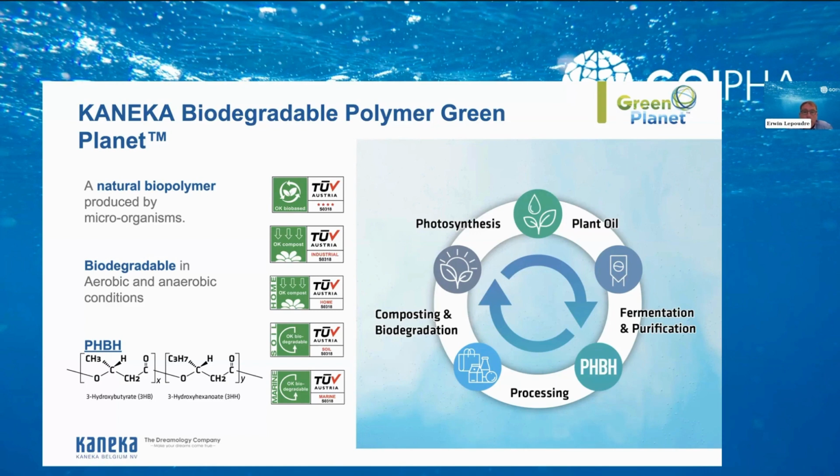Kaneka focuses itself at the moment on the PHBH structure. So PHB is probably the most well-known polyhydroxyalkanoate, but microorganisms as well have the capability to produce some co-monomers of PHB, like with the hydroxyhexanoate, as well with the valerate, etc. Kaneka focused on the PHBH concept, however, can vary the co-monomer ratio, and by varying the co-monomer ratio, we are capable as well of making polymers with different mechanical properties. Next slide, please.